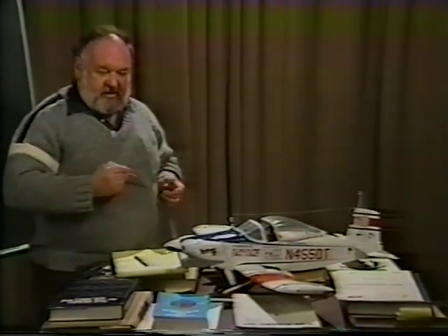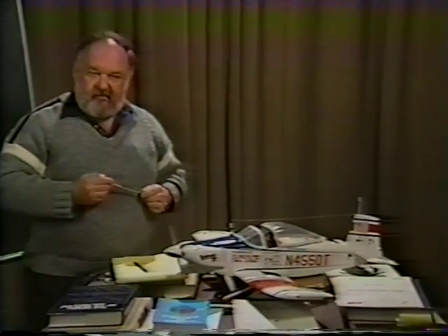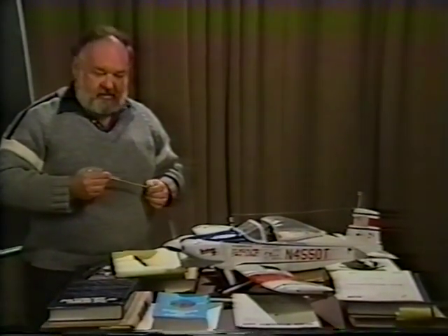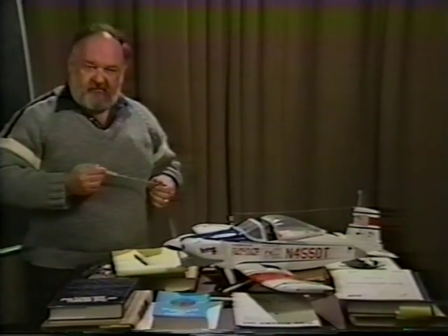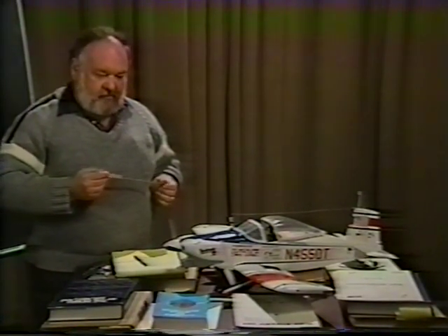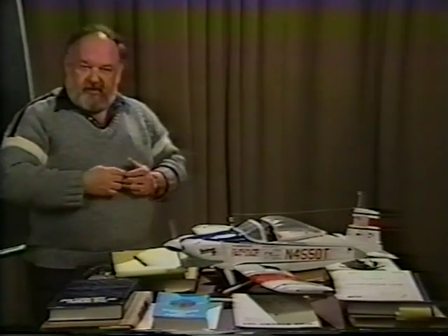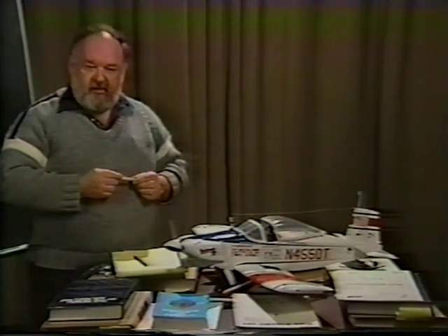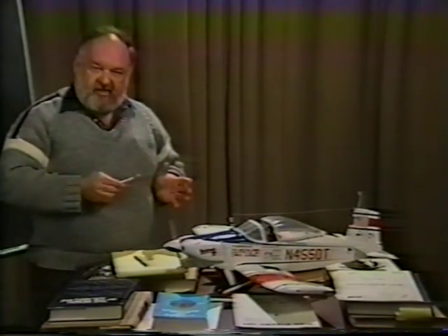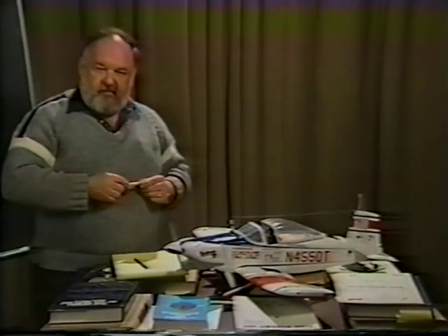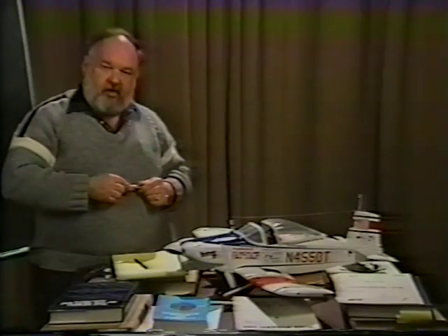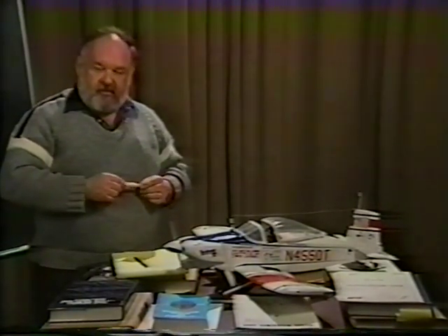I'm not sure really on the T-18 whether he has any twist in the wing. He may have one or two degrees of washout on it that would assist in giving the proper stall pattern all the way around. But it does represent a typical home built, and it does represent a good design, and one again where you do have to compromise. What you'd like to get in one aspect may be structurally or cost-wise more difficult to make, so you balance that out with the overall design of the airplane.